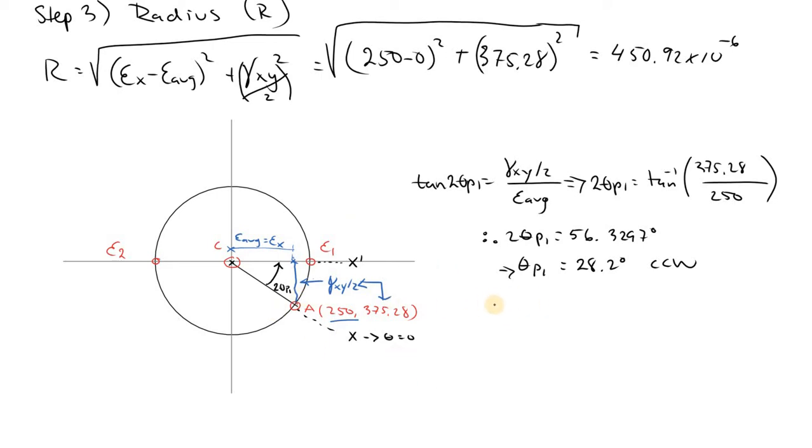And lastly, before we draw out our element, the principal strain. Pretty neat, and only when we have the center point at 0,0, so at 0 shear and 0 normal strain, the minimum principal strain is simply the negative radius. This is just this distance here.